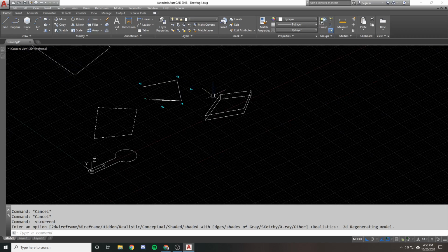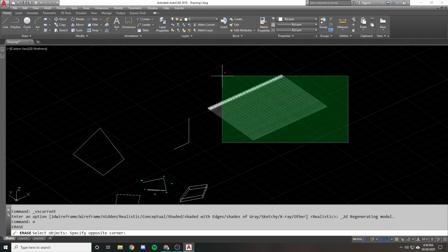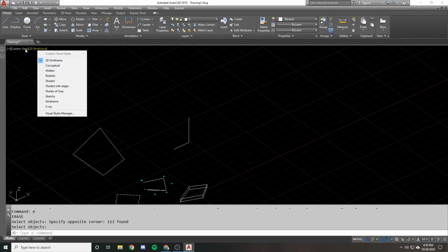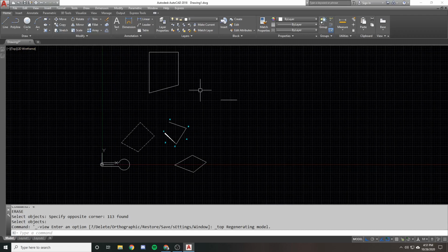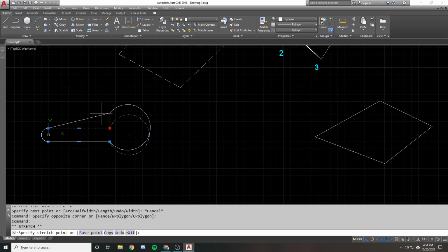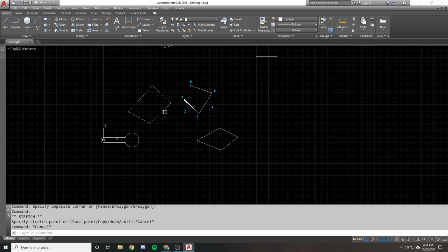So that's one instance. I can give a personal example of why I would want to use a multiple P-line edit. But in most cases, the majority of the time, your P-edit and your P-line is going to be much more simple. It's going to be modifying rectangles or just drawing a quick P-line this or that, or doing a shape like this and then converting it into a polyline that you can then further edit or give thicknesses and things like that too.